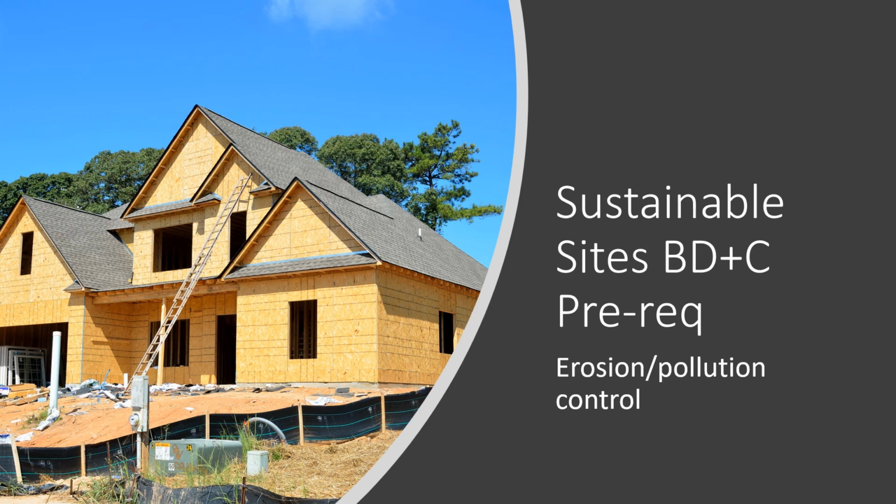Some of the BD&C rating systems have additional prereqs. For example, the rating systems for health facilities and schools require an environmental assessment, and operations and maintenance instead has a prereq to develop a site management policy. It's important to know some of the strategies that can be used to meet the prereq or the credit requirements. Some of the strategies that can be used for erosion and pollution control include using mulch, berms, straw bales, silt fences, and erosion control blankets.